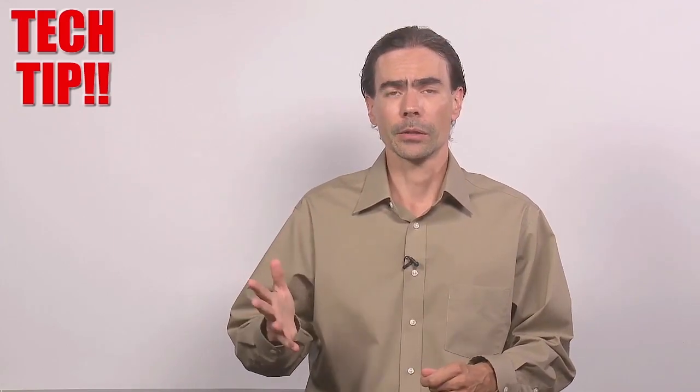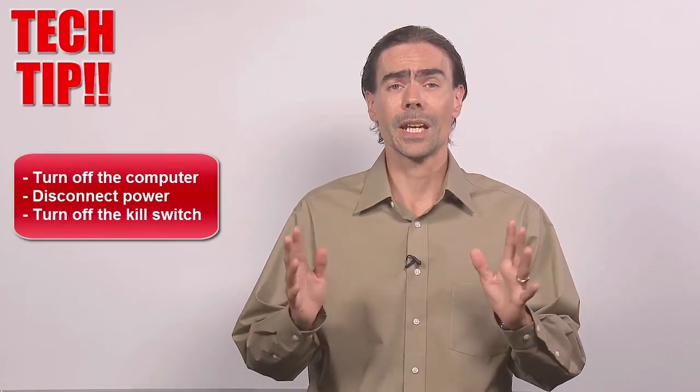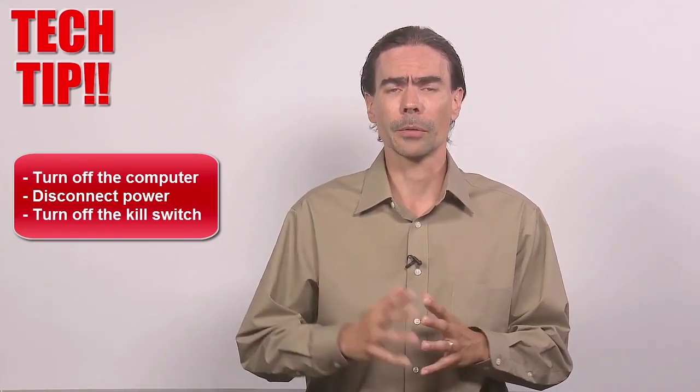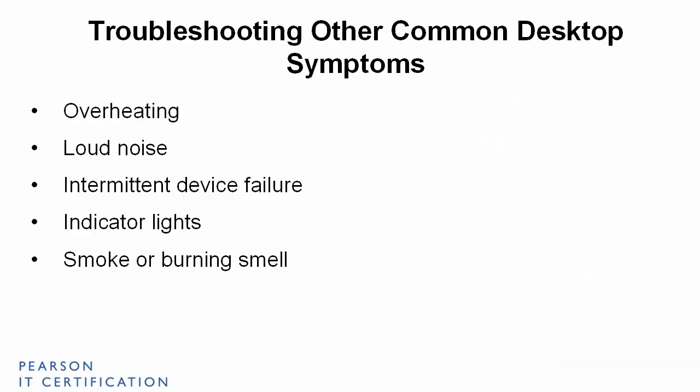Smoke or burning smell. Previously, we said that you're going to use a lot of tools when troubleshooting a computer. But the best tools, we said, are your eyes and your ears. Let's add to that your nose. If you ever smell something burning from a computer, or if you see smoke, you're going to want to turn it off and disconnect it right away. So if you see any type of smoke, or if you smell a burning smell or a strange odor coming from the power supply, you want to turn it off and disconnect it immediately.